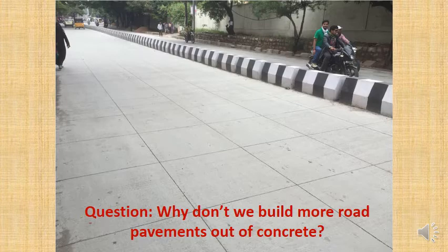Concrete also does have a little bit of a disadvantage too. Look at that concrete road just there. Do you notice all of those squares? There's little grooves cut into the concrete. What are those? Do you remember from studying concrete with me? Well, those are contraction joints. Those contraction joints are there so that when the concrete is drying and hardening, it doesn't form shrinkage cracks. It's basically dividing the concrete up into smaller blocks so shrinkage cracks don't emerge.